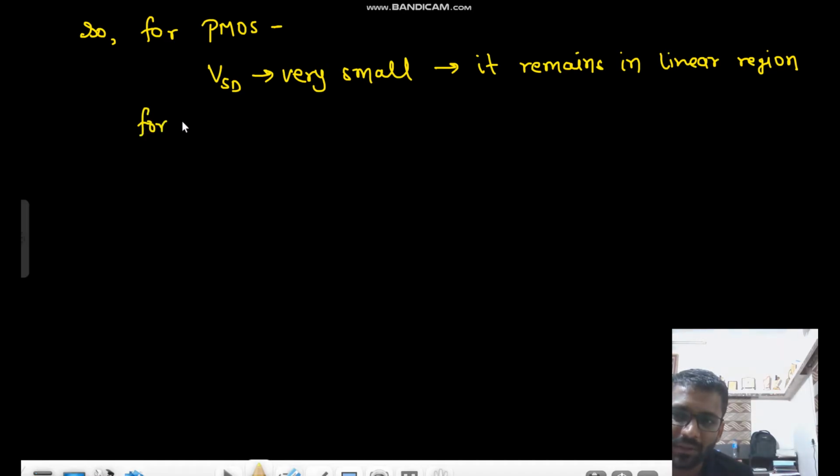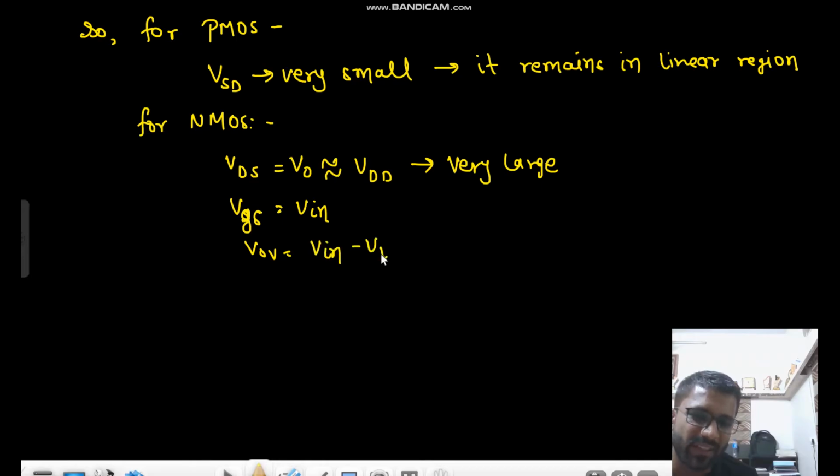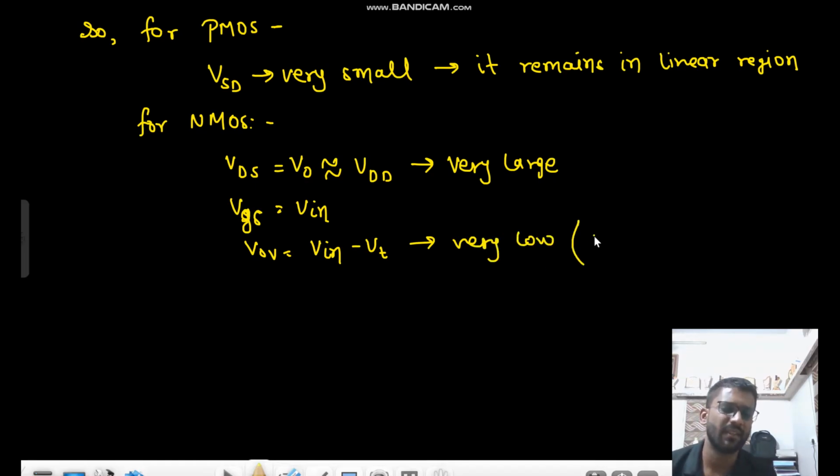For NMOS, what is VDS? That is V naught. That is nearly equal to VDD. That means it is very large, right? What is VGS? VGS is V in. Okay, and what is V overdrive? It is V in minus VT. So it is very low, right? Because V in is just greater than VT.